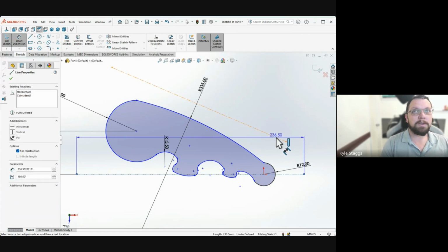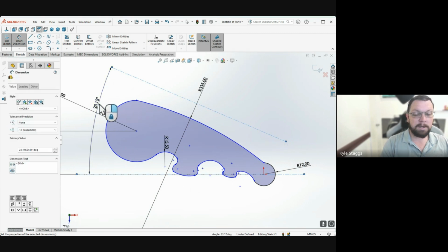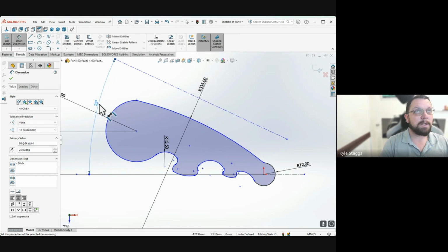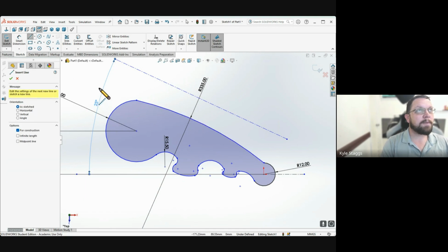You might need this to be different by, say, 25 degrees or something like that, right? So you can set the angle difference relative to a center line at 25 degrees. You can do it at other angles as well. But if you do it that way, you can then do another center line, and you can make it parallel to that one.